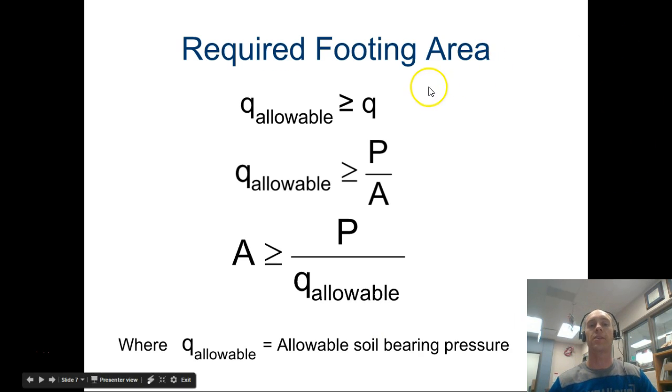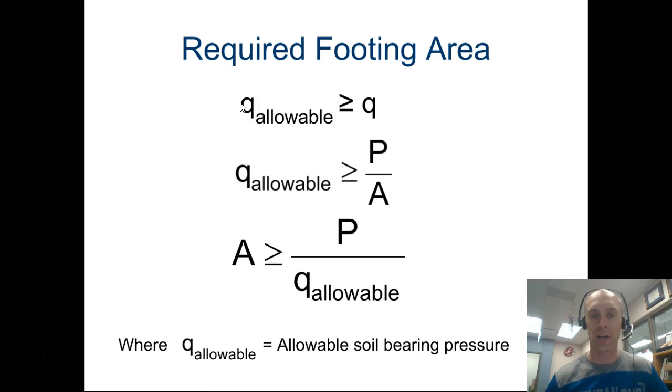So to do our calculations, to figure out your footing area, remember Q equals P over A. You just took a screenshot of that, I wrote that down.